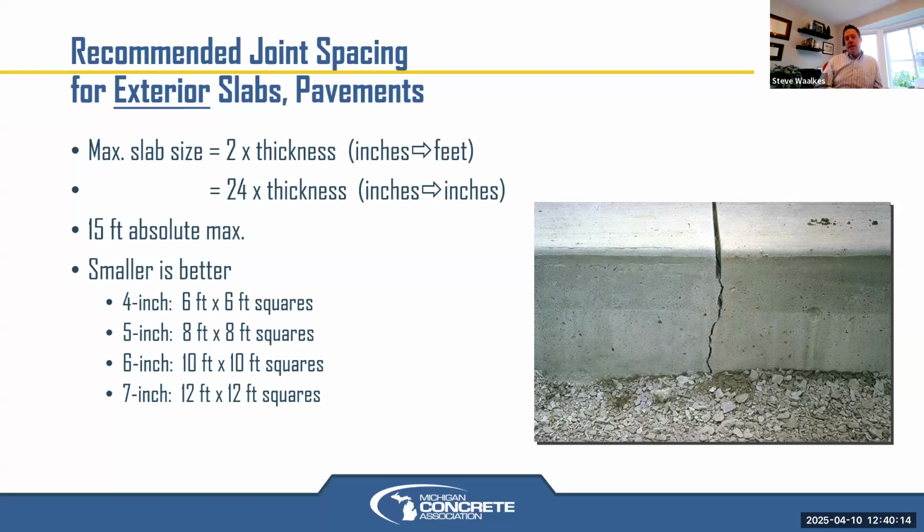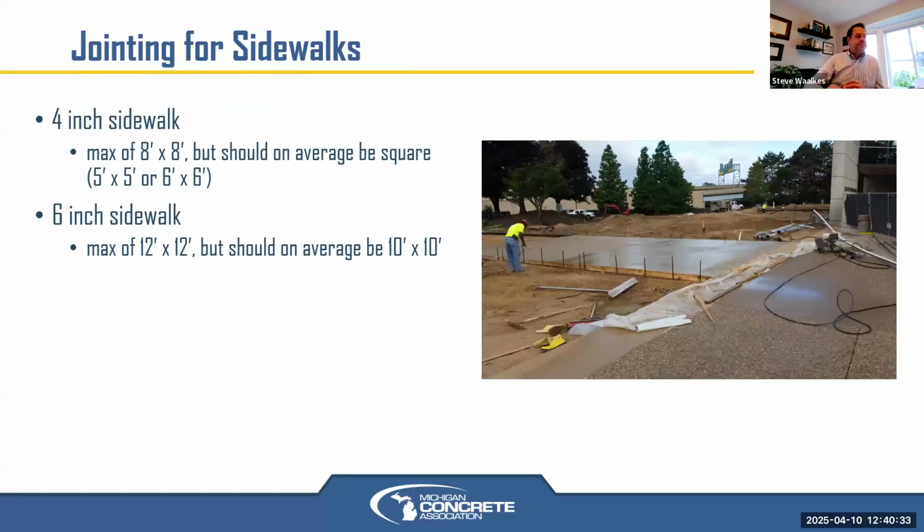And we've seen some agencies just switch to 5-inch and then do the full 10-foot by 10s if it's a 10-foot pathway. But regardless, that's kind of the max that we'd recommend. Smaller is always better, like we said, and you can make adjustments if needed. And 15-foot for normal situations, like we said, is your absolute max.